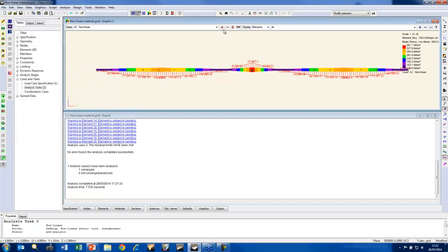I call up the stress results. And we can see for the linear analysis, we're getting way over capacity at the center. In the non-linear, we are apparently getting excessive stresses at the hinge in the middle. Reality is not quite correct, because the stress calculation is a post-processor, whilst the analysis is taking into account the elastic plastic zones moving across the elements.